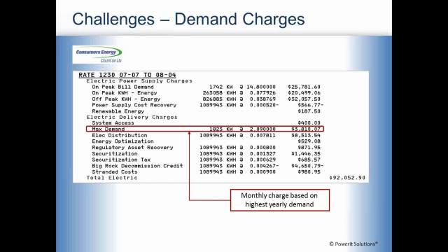The maximum demand charge for a facility was calculated by the highest 15-minute period on any given day during the week. They would take that, multiply that 15-minute of usage out into an hour time block, and that would set the maximum demand for the capacity of the plant.